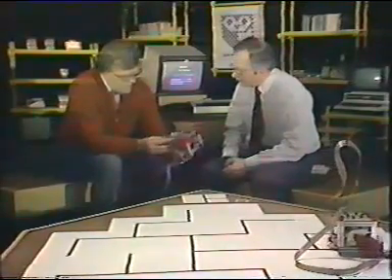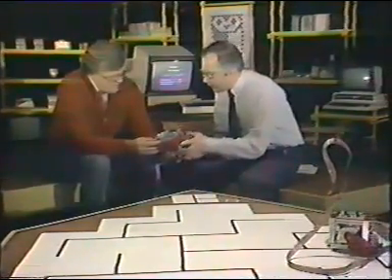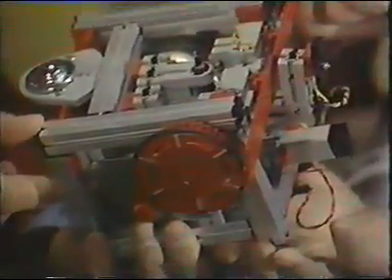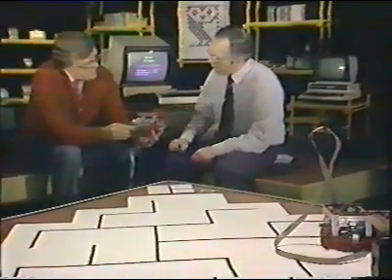So those are the input devices, and we've also got some output devices here. Right, well, we've got two output devices. There's a stepper motor here and a stepper motor over here, and as well as that, there's a device for moving the pen up and down. So, stepper motors and pen up and down. The stepper motor just moves it round one click at a time at about 7.5 degrees. When you give it one digital pulse, it moves, as you say, a very small angle.